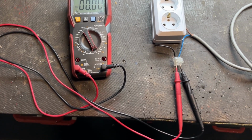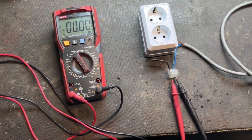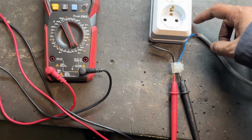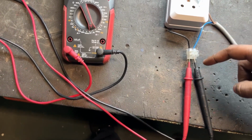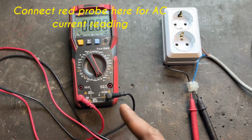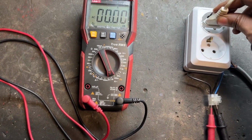Guys, I have made this arrangement to show you how to measure the current for an AC. So I'm going to measure the current of this fan. You can see this is in series. The multimeter is in series. This brown wire is connected here. This black wire is connected here, and this blue wire, this incoming wire that is coming all the way from a multimeter and then goes from this black wire. So I will connect a fan.